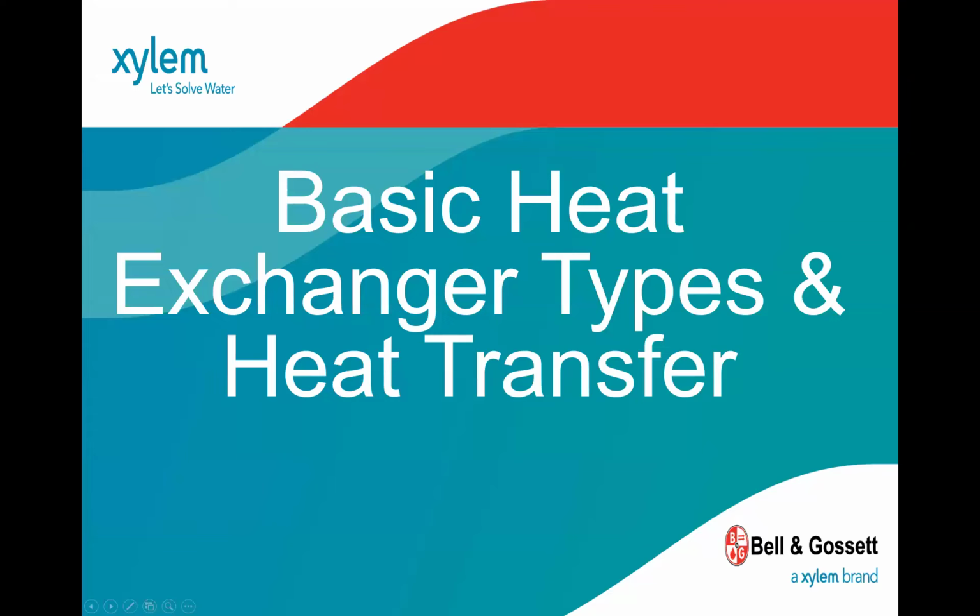So with the brazed plate units, really just the plate types in general, there's a high heat transfer rate, so you have a nice turbulence to it. There's a recommended minimum of a 2-degree approach. So remember that's quite a bit lower. It's great for temperature cross. A disadvantage is obviously limited configuration.